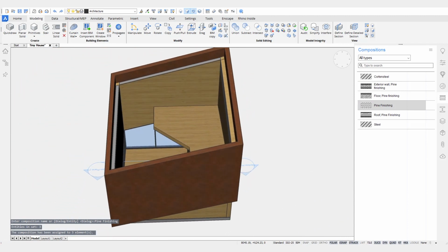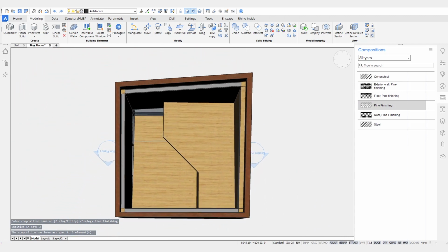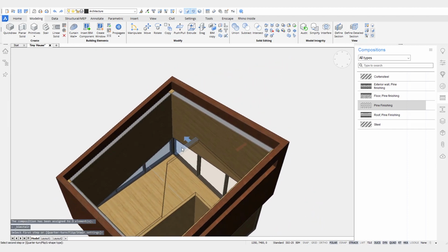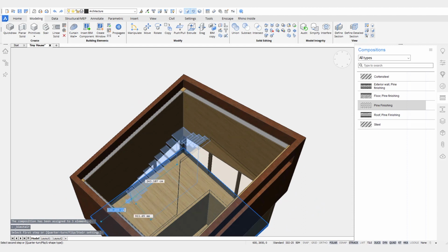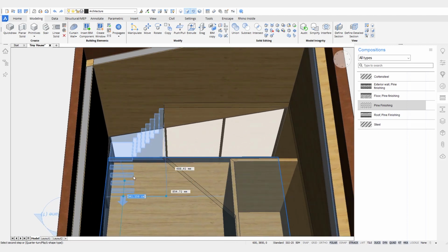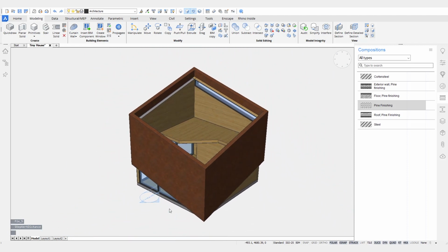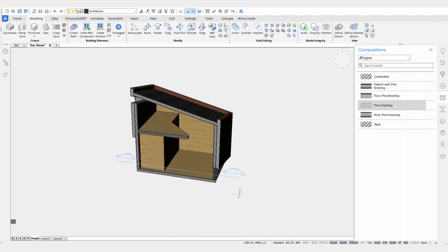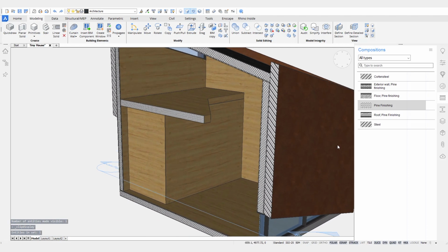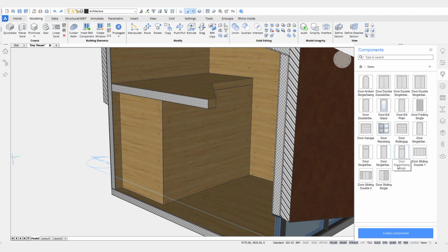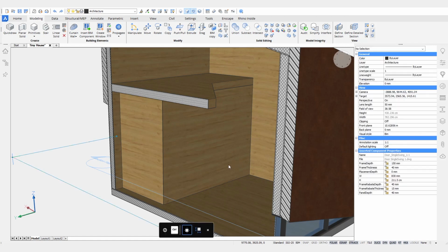And if we want to be able to get on top of this mezzanine, of course, we would need a stair as well. So I can use the BIM stair tool for this. It snaps to this edge here. Already get a preview. But actually, because of the limited space here in this building, I'm going to use more kind of a ladder instead of a staircase. So just a very steep staircase in this case. And obviously we need a way to get into the bathroom as well, so I'll use a library object, a door, to get inside there.